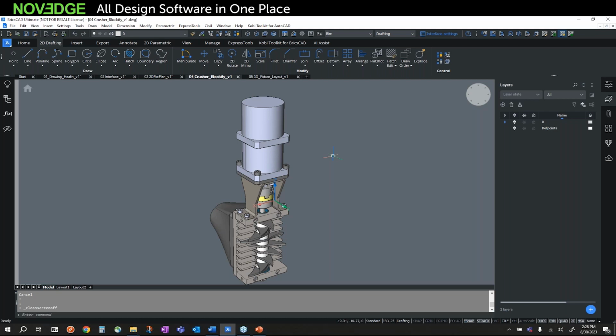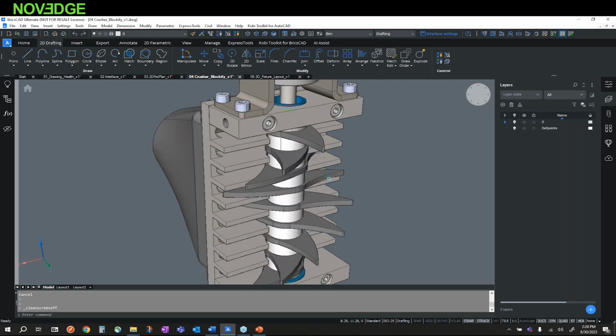In this particular drawing assembly, there are some blades on the assembly that have been exploded by mistake. The blades have been reset to simple 3D geometry, and they obviously increase the size of the drawing and make it difficult to manage. BricsCAD uses the familiar concept of block definitions and block references. If I hover over some of these blocks, you can see that this is just a 3D solid. This got exploded. This one happened to have retained its block reference, but there are a variety of these blocks out here that got exploded. So let me go ahead and isolate those.